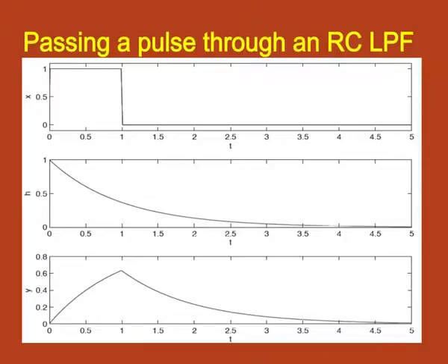In order to understand in detail the effect of these kinds of distortions, first we need to characterize the signal occupancy or frequency occupancy of a signal, because we said that for a distortionless transmission, the amplitude of the transfer function has to be constant over the frequency band where the signal has non-zero amplitude. Also, for phase distortion, we should have linear phase over the frequency band for which the signal has non-zero amplitude. So, first we will define the frequency range which is occupied by the signal.